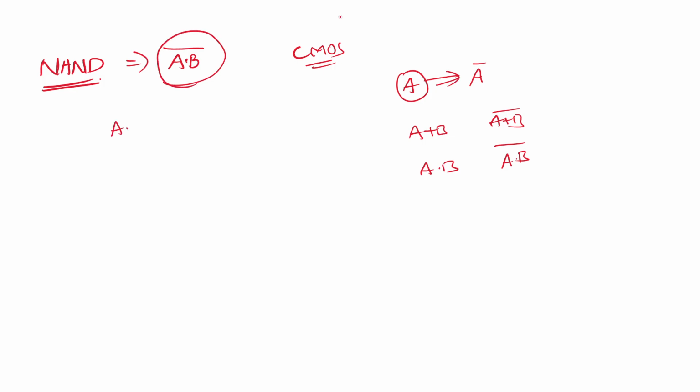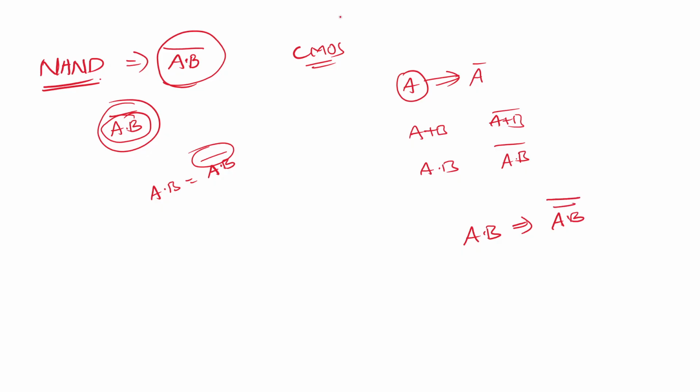So that's why when you are going to design a NAND gate, (A dot B) bar, you just design the A dot B only. Then automatically you get the complementary output of the bar. If you have some doubt, if there is no bar, A dot B only, then you have to include the bars. What are the two bars you have to include? If we cancel them, then you again get the same thing. So A dot B double bar you have to add. For this operation I am explaining, one bar is the same as this, and another bar is going to be applied to the equation.